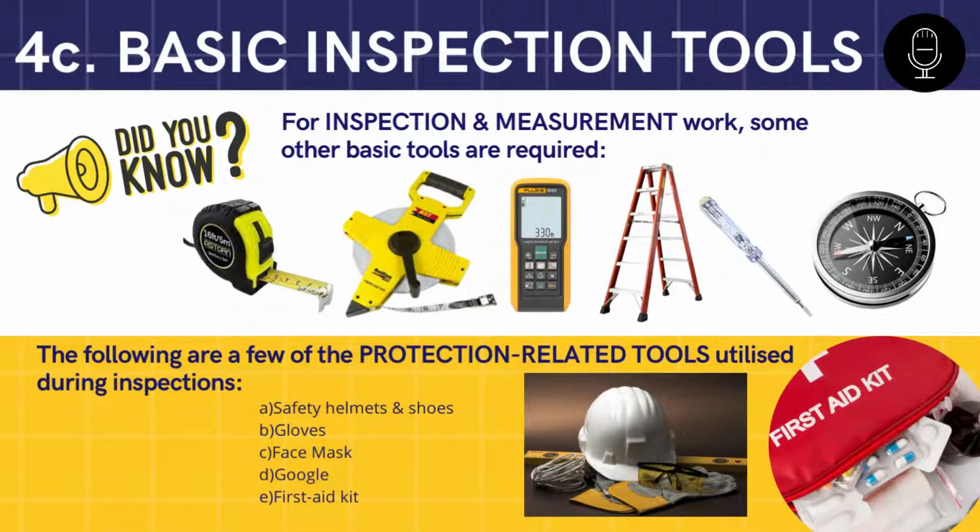Basic inspection tools. Did you know for inspection and measurement work, some other basic tools are required? For example, to measure the length of the structure, we need a measuring tape or laser distance. Ladder to assess the higher structure, test pen, compass, and so on. Meanwhile, for the protection-related tools in building condition assessment, there are some tools that are required. For example, we need safety helmet and shoes, gloves, face mask, goggles, and first aid kits.